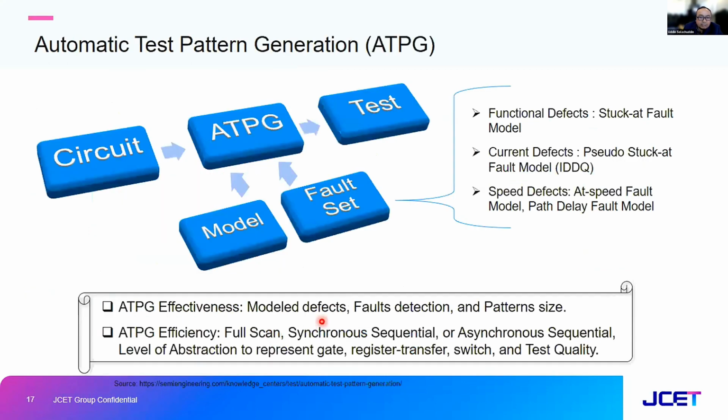So here's almost the output that the OSAT will need. With your selected ATPG, which is basically the tool you use to produce the test vectors and test patterns, you will work with the OSAT test development engineer on how to define your test plan, test list, etc.